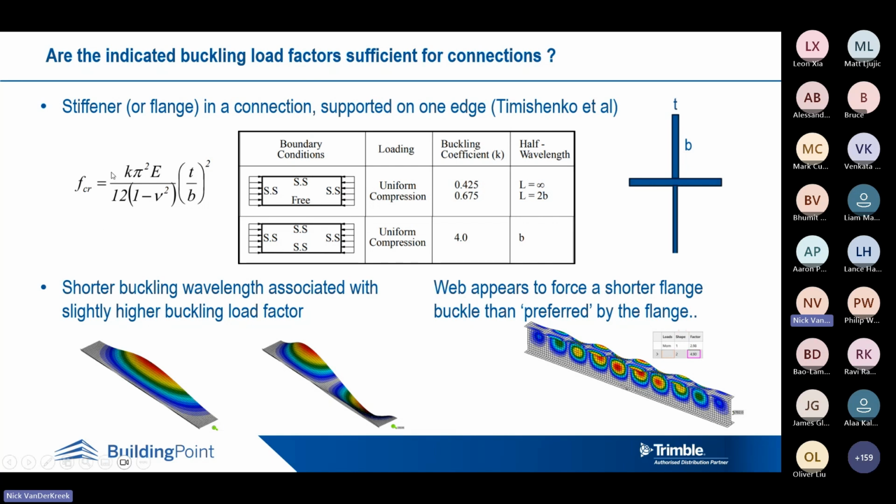So looking at the Timoshenko buckling stress and so on, it uses the b on t, or the inverse here. So b on t, the width to thickness ratio, and of course in our code, we modify that with the yield stress calculation compared to 250 as well.